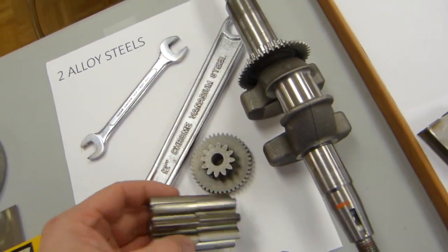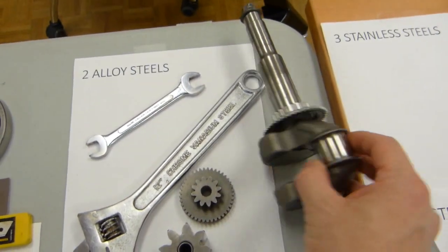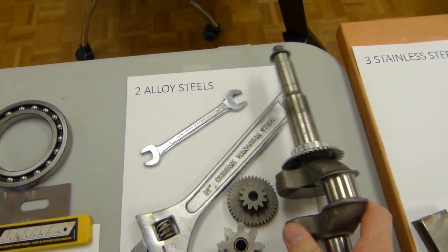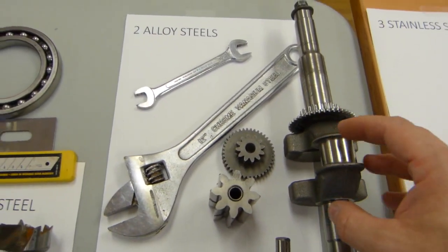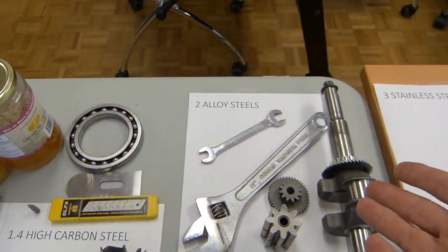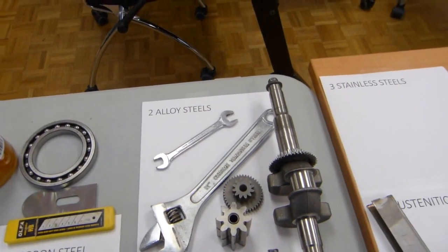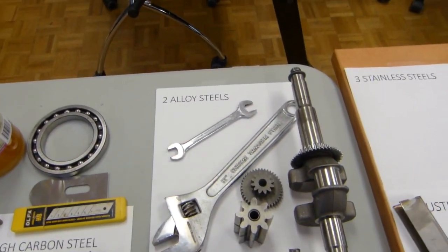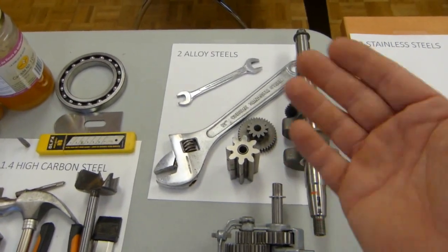They make gears and gear teeth out of alloy steels and metal that's case hardened, such as the bearing journals on a crankshaft. Often these products are hardened in special manufacturing steps so that the outside of these surfaces is hard and the inside has a little give so it withstands the forces that are placed on it in normal operation inside the engine. Massive amount of shock loading from the combustion process that's cyclic in its nature, so it's not evenly loaded. It's bam, it's loaded at one point and then not for a little while, and then bam again loaded, and so because of its cyclic loading, it's a composite product.